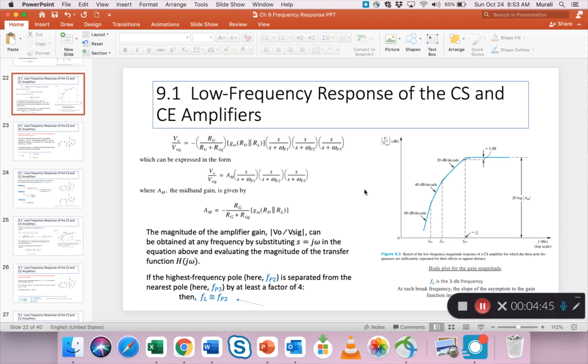So these are some basic rules, but using these rules and the formulas that we found for CC1, CC2 and the CS capacitor, the three capacitors, we can calculate the capacitance. So the two issues are obviously related to each other. You want to know what low frequency you can get to as the cutoff frequency FL.